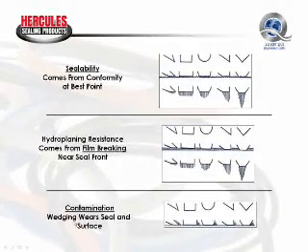Another thing to consider when selecting seal lip designs is the amount of contamination that is in the system. B lips and round lips typically are not very good to use with contamination because the contamination tends to wedge itself into this interface area between the sealing surface and the seal lip. Same thing happens with the round lip. So it's more wearing on the sealing surface and more abrasive and wearing to the seal lip itself.